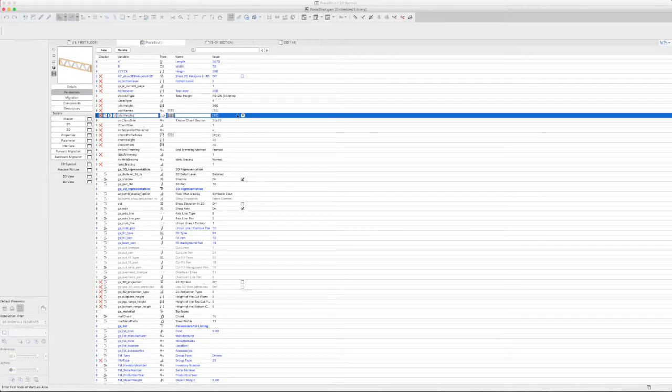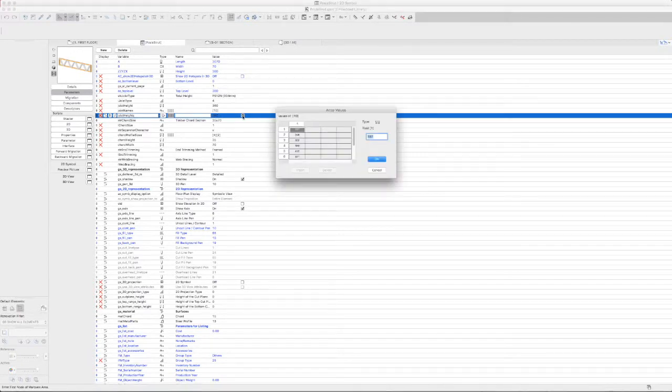So if you click on joist heights and then click on this symbol over here, it opens up a table of array values that you can type in. I've just typed in the ones that are available in Australia, overwriting the ones that you will have there. These are the right dimensions that you really want: 197, 248, 302, 360, and I'm not too sure, I think 360 is the largest one in Australia, but you can probably tell whether I've adjusted that one.